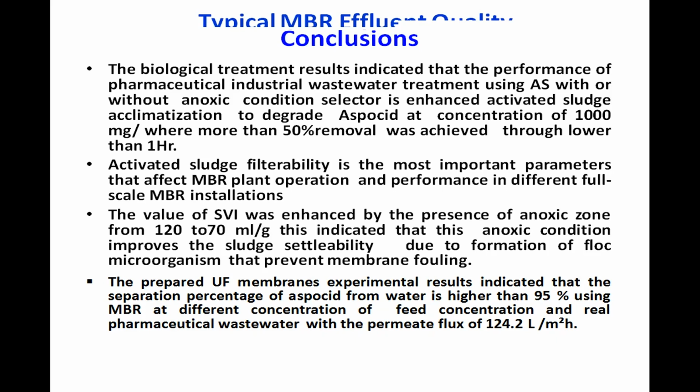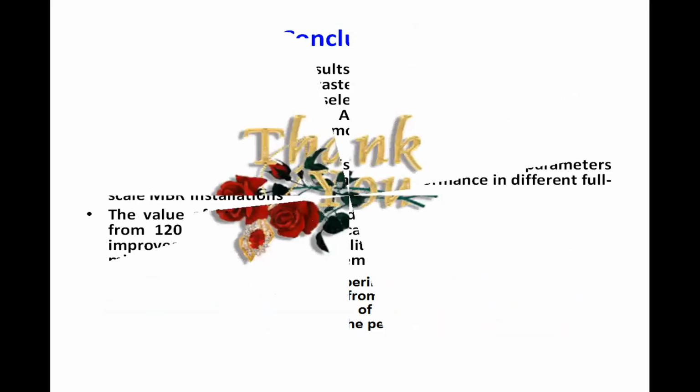The prepared UF membrane experimental results indicated that the separation percentage of the drug from water is higher than 95% using a membrane bioreactor at different concentrations of feed and real pharmaceutical wastewater, with a permeate flux of 124 liters per square meter per hour. Thank you.